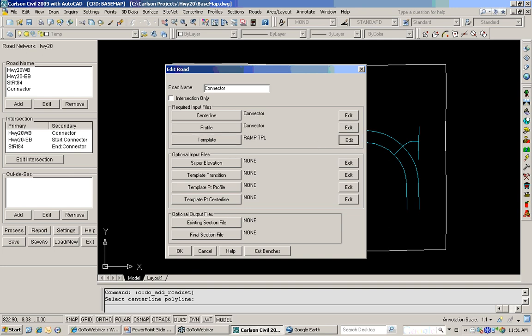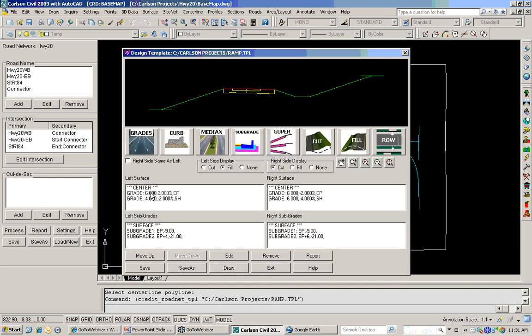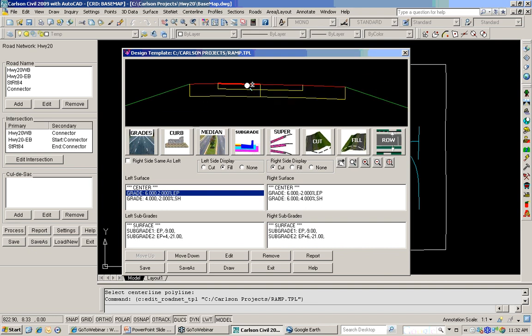About the only thing that's really different than this one is that the pavement width is actually a 12-foot wide driving lane here, and it is actually sort of asymmetrical. It's got a positive 2% slope going up here and a 2%, so it doesn't have a crown. It's just a flat grade across here, and it's got a narrower shoulder.